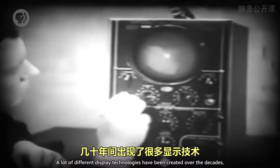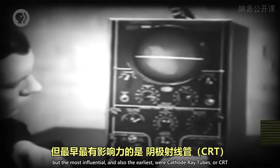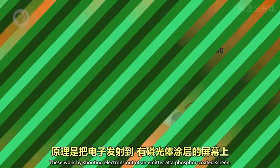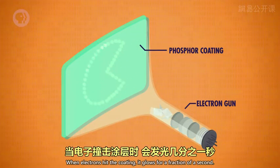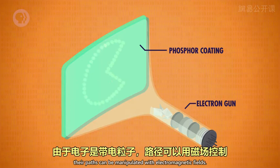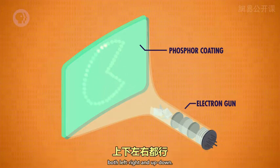A lot of different display technologies have been created over the decades, but the most influential and also the earliest were cathode ray tubes or CRTs. These work by shooting electrons out of an emitter at a phosphor-coated screen. When electrons hit the coating, it glows for a fraction of a second. Because electrons are charged particles, their paths can be manipulated with electromagnetic fields. Plates or coils are used inside to steer electrons to a desired position, both left, right and up, down.